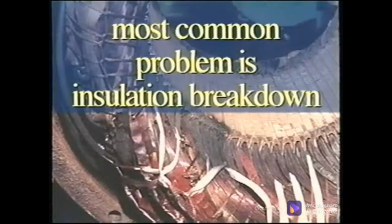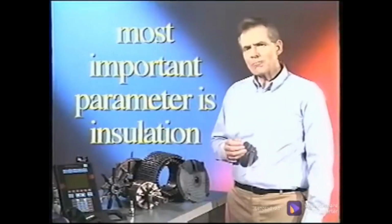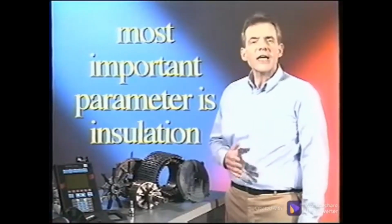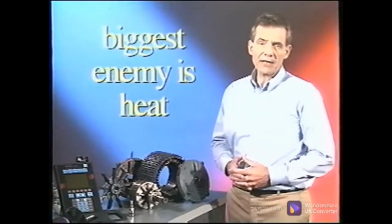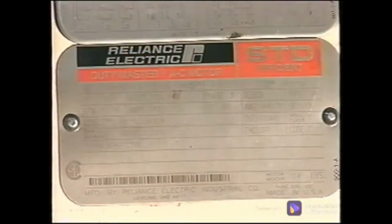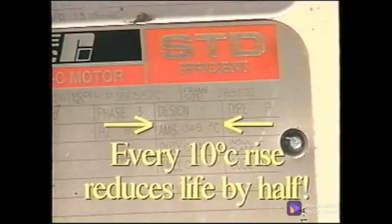The most common problem is insulation breakdown due to excessive heat. The single most important parameter influencing the reliability of electric motors is insulation, and the single biggest enemy to insulation life is heat. In fact, for every 10 degrees Celsius rise above the nameplate temperature rating, the winding life is reduced by half.